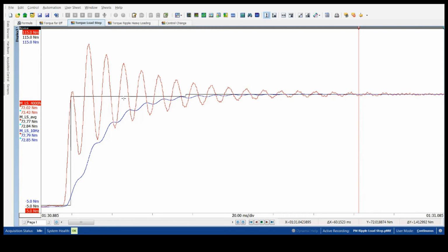This is because we are taking a nice time average of all the points that are going equally higher and lower than the average even during the settling time. This gives us a reliable number for efficiency readings, but no sense of dynamics. The cycle-based nature of the calculated average makes this a very accurate solution even when doing dynamic testing, but you do not get the peaks and valleys that you see with the full bandwidth torque.